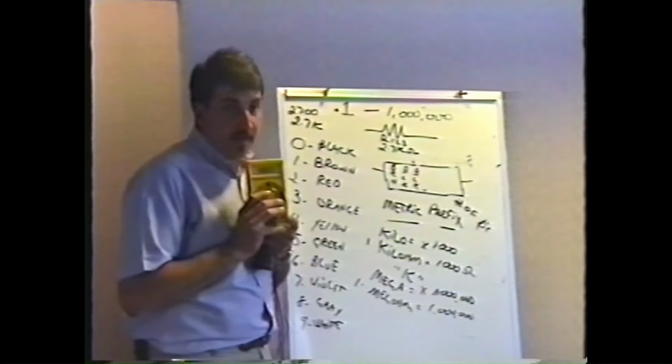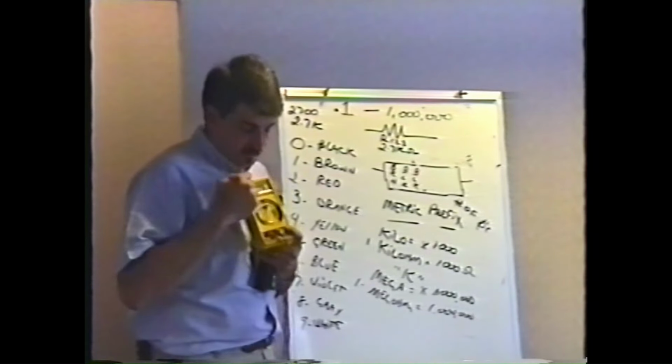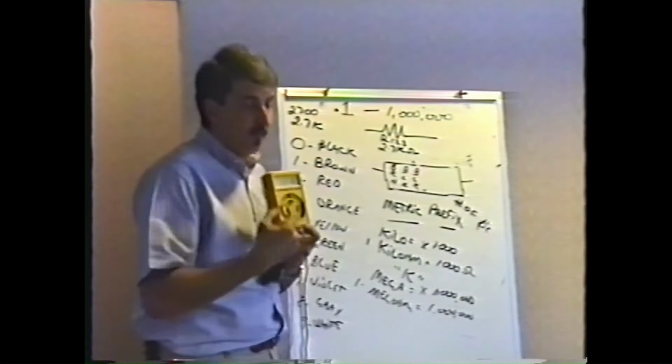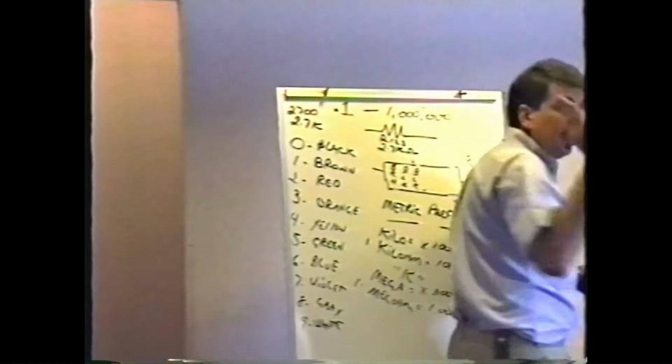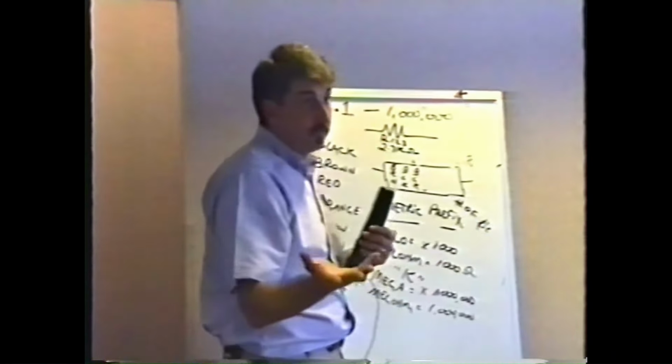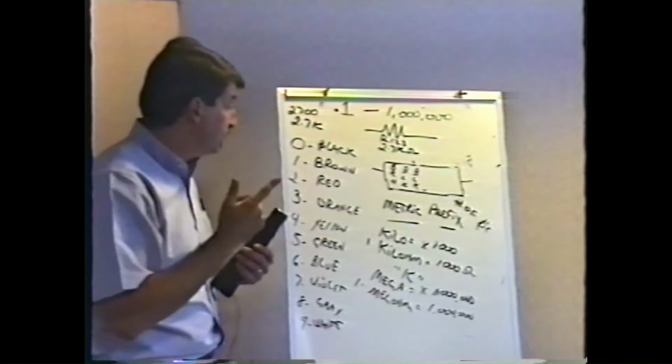Now, this particular meter says OL on it. That's when the resistance is higher than what you have it set for. Other meters might just have the number 1 with no digits after it. You'll see when we start doing the resistor lab how simple it is, and we'll do that in just a few minutes.